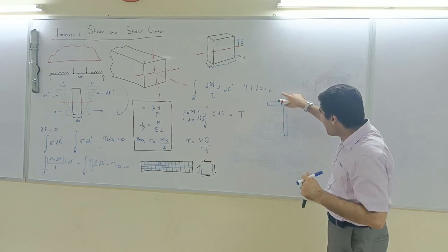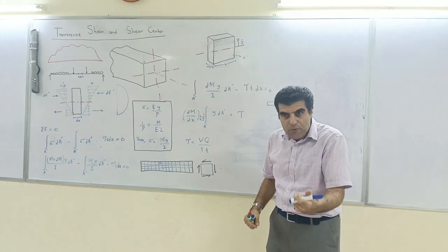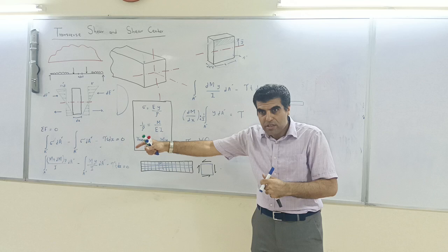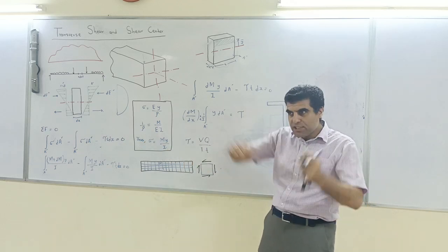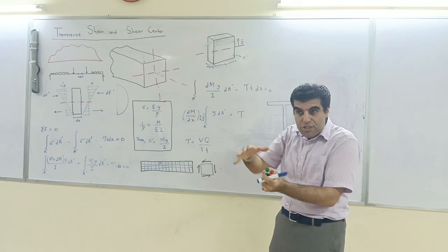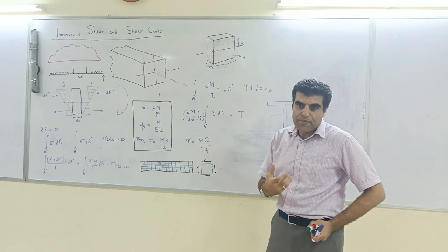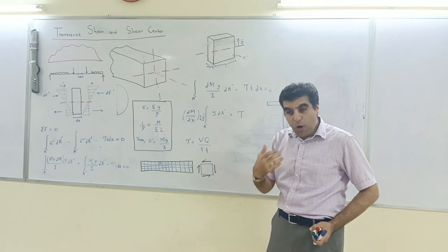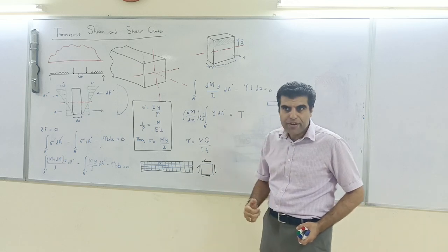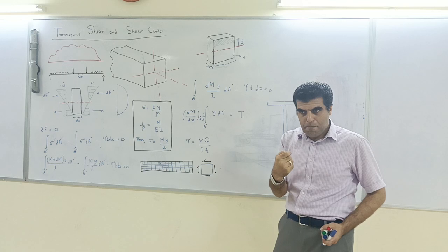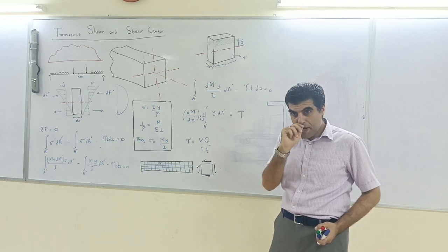It can be like, imagine I have nailed it over here. I have put a series of nails over there. Now I want to find out how many nails should I put in order to take the horizontal shear. So that's why when I join different components together, I produce weak zones. And those weak zones are actually points which can fail. Those are the regions which can fail under shear, and I have to check them, okay, whether they fail or not. You understand my point?